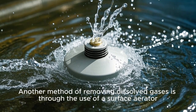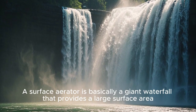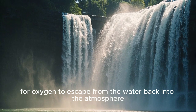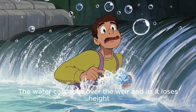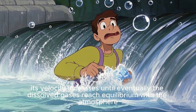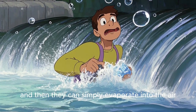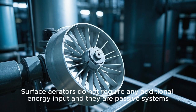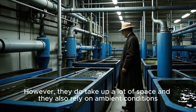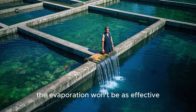Another method of removing dissolved gases is through the use of a surface aerator. A surface aerator is basically a giant waterfall that provides a large surface area for oxygen to escape from the water back into the atmosphere. The water cascades over the weir, and as it loses height, its velocity increases until eventually the dissolved gases reach equilibrium with the atmosphere, and then they can simply evaporate into the air. Surface aerators do not require any additional energy input, and they are passive systems. However, they do take up a lot of space, and they also rely on ambient conditions. That means that if there's no wind, the evaporation won't be as effective.